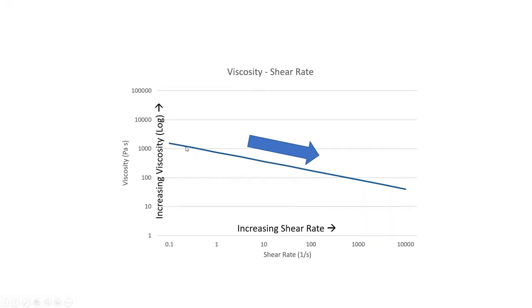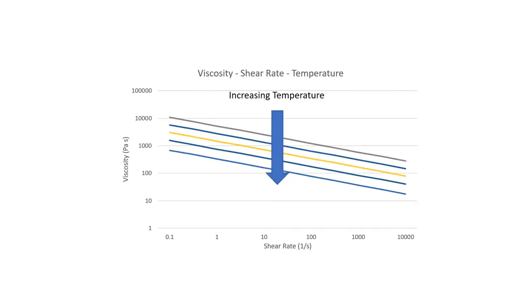With most materials, once we subtract out the paint effects and we're in that high flow, high shear levels, we generally see a very linear approach to the materials. Not every material, but generally that's what we see. It's a rule of thumb. And that temperature increase is very important to measure. As the temperature of the material increases through the flow path, we see that decreasing.